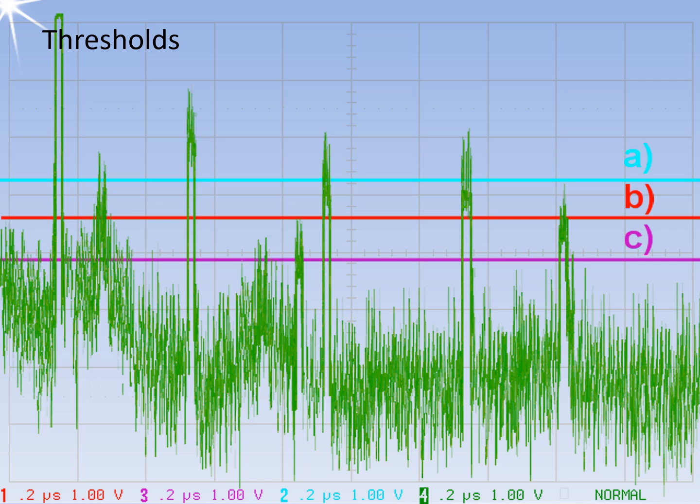However, even at this point, the probability of detecting a target is only 5 out of 6, or about 80%, and minor disturbances still occur at close range. If the thresholds are represented by a constant DC voltage, the probability of a false alarm is much higher at close range than at a greater distance. Simultaneously, the probability of detection at a larger distance is much lower due to the threshold being set too high.